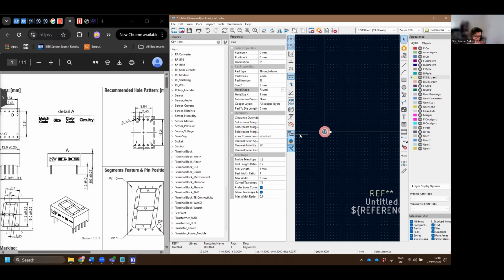Then we have everything else I think we can leave. Yep, cool. All right, so then from there, we can just copy and paste that a few times, and we can just adjust the position accordingly. So from our data sheet, each one needs to be 2.46 away from the previous one. So that's all in mils. So we just need to keep popping them along another 2.46 further away each time. And yes, I am doing this with my calculator because it is too late in the day.